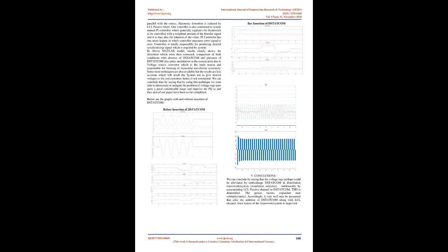In addition, the converter is based on some sort of energy storage, which will store and thus supply the converter with a DC voltage. On the DC side, voltages are supported by a capacitor. The capacitors are sufficient to handle the charge or discharge current which accompanies the switching sequence of the converter valves, and also shifts in phase angle of the switching valves, with no significant changes in DC voltages. For the purpose of discussion in this paper, the DC capacitor voltages would be assumed constant.